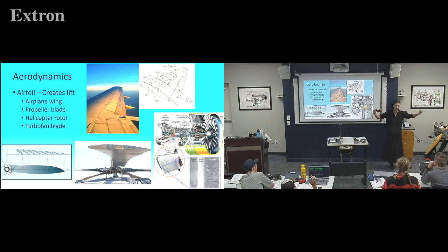Alright, we got a couple people saying it'll increase and a whole bunch of people not participating. But yes, lift will increase. What about drag? Will drag increase or decrease? It will increase, yes. It increases until our air can no longer stay attached to our airfoil. We lose lift, and now drag is a big monster, and down we go, unless the pilot recovers.